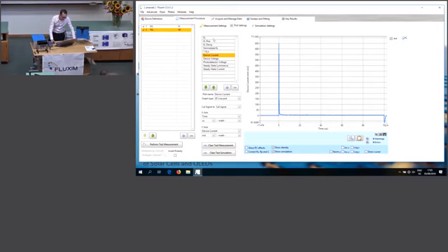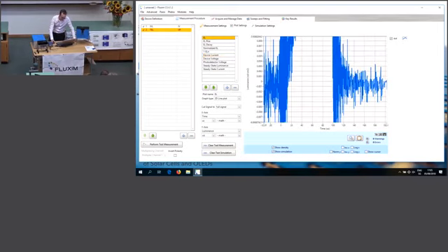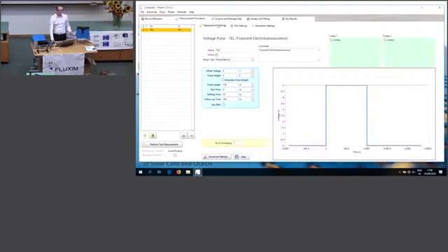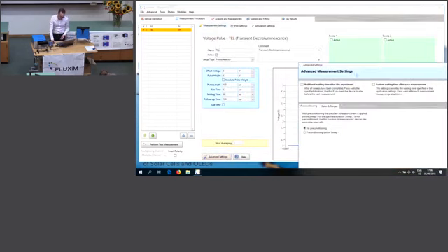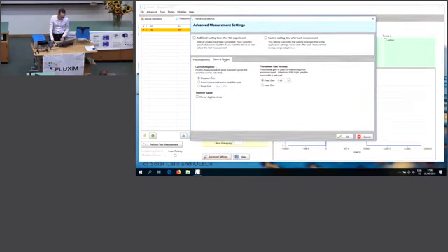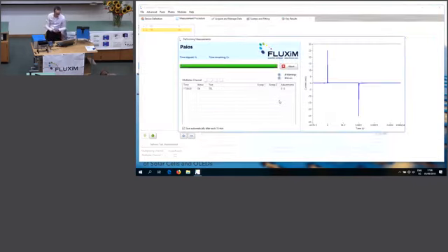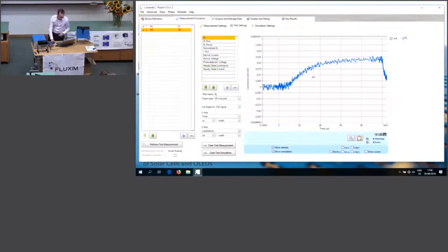What we can do here is look at the electroluminescence signal, and you see now there's some noise, because apparently the signal is very weak. There's some noise at the beginning, and then the EL signal rises. To improve the signal quality, we can say we want to use a certain gain, since the photodiode has different gains. When we measure it now, it looks much better.